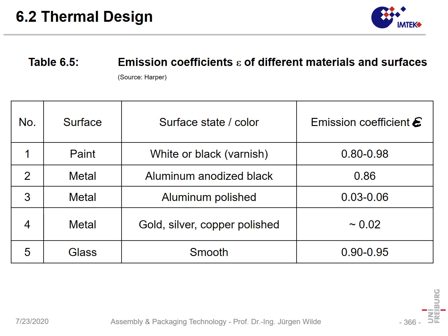So you could say when the emission coefficient is low, you will also make a large relative mistake in the power you estimate. If aluminum is black anodized, like for instance many heat sinks are of black anodized aluminum, then it has a coefficient of roughly 0.86 or something like that.